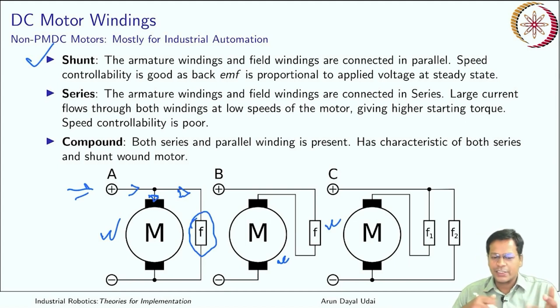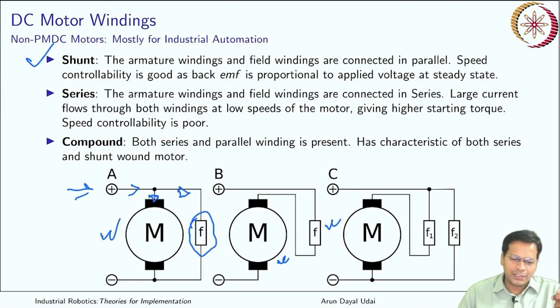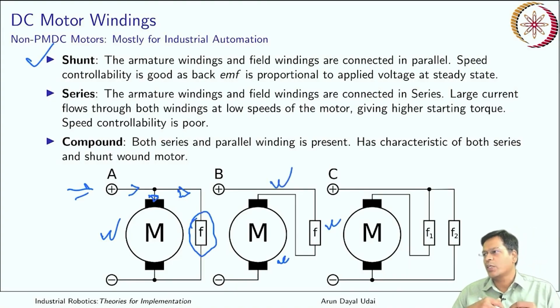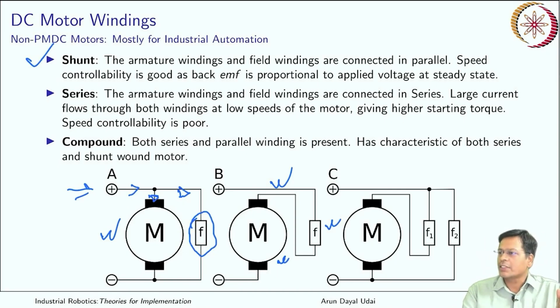Once the rotor takes up speed, it takes a small amount of current, right. If it is no load, it can draw less current. So this type of characteristic is also useful. Let us say you want a starting motor for your car, where the starting current is required to be very high, but in that case normally a PM DC motor is used. Anyway, that is there.